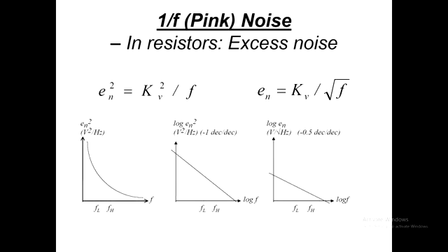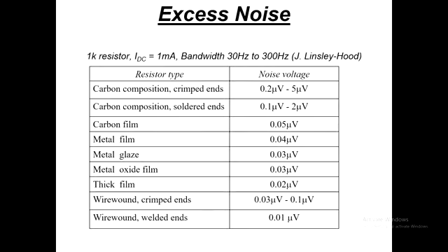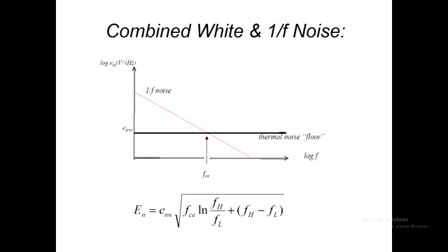We would be given that value, wouldn't we? No, because the mechanics of all this say that if we equate that noise level where the white noise part and the 1-on-F noise part are equal, then we can eliminate that K. In the sense of the two noise profiles that intersect, you can cancel that. And that frequency where they intersect, we'll call the corner frequency.